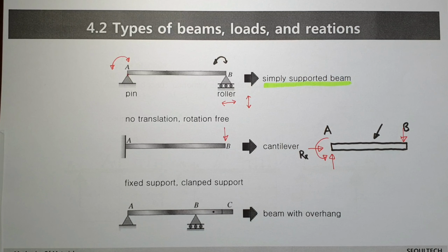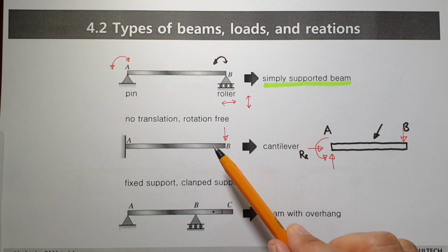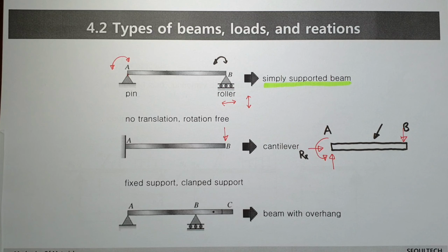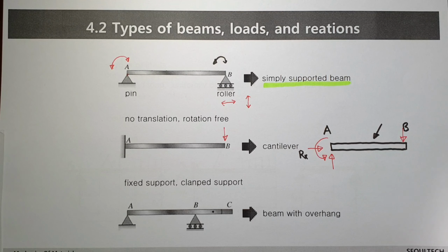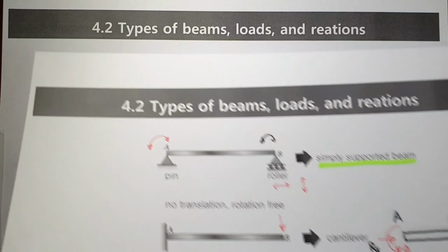If you consider a beam, the conditions on the left side, middle, or right side are different. When you know the difference between them, then you can easily draw the free body diagram, and you have a very powerful tool to solve problems.